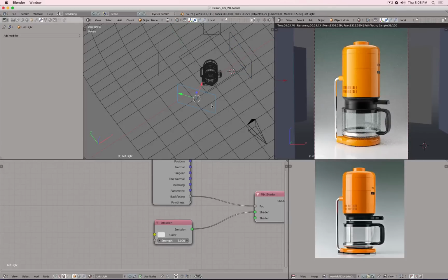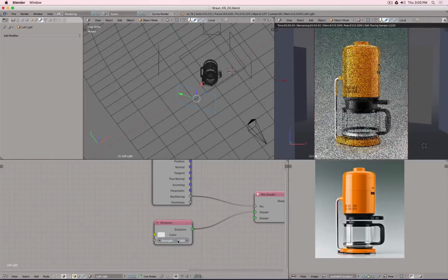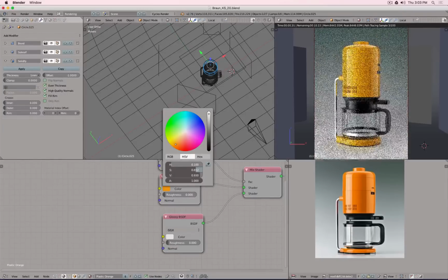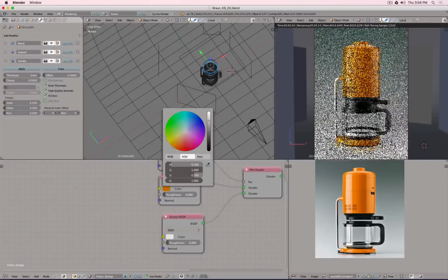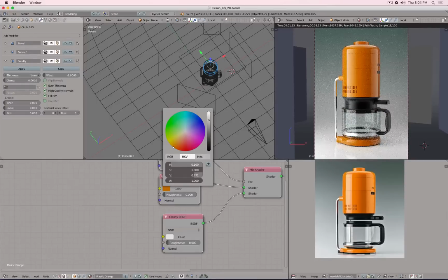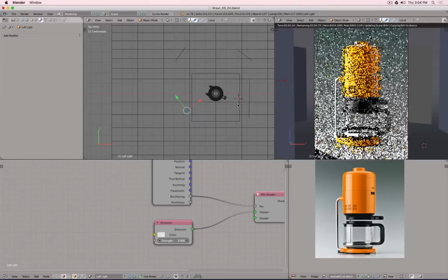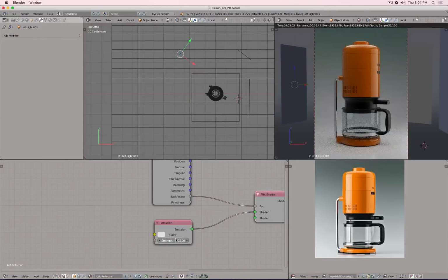So let's take a look at here. This light, it is actually too strong. It blows out too much light. Or maybe I have to adjust the color. This shouldn't be so saturated, because the more saturated it is, the brighter it will get. Maybe let's go this way. There it is. Now, a very bright color, when it gets a lot of light, will wash out very easily, and if it's a darker color, it will not wash out as easily when it's illuminated with light. Tick brighter. Yeah, maybe like this. And let's see what's happening with our reflection light here. There, maybe a 1.